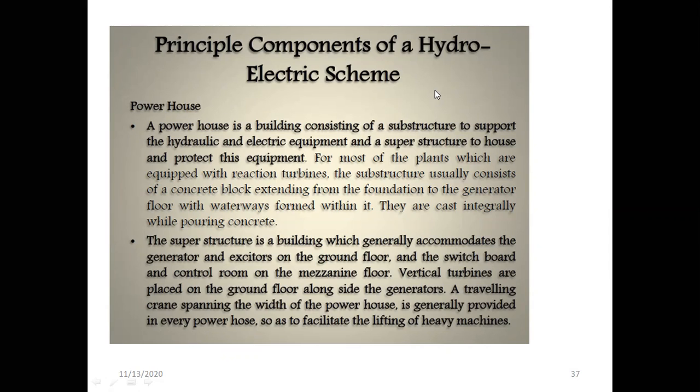Then I also gave an exploded picture and a cross section of an example of a reaction turbine. I gave an example of the Kaplan, and I said this one makes use of the velocity of the water as well as the pressure difference. The reaction turbine was fully submerged in water, unlike the impulse turbines, and the pressure difference as well as the velocity of water led the runner to rotate, and that runner was connected to a shaft that was connected to the rotor of the generator.